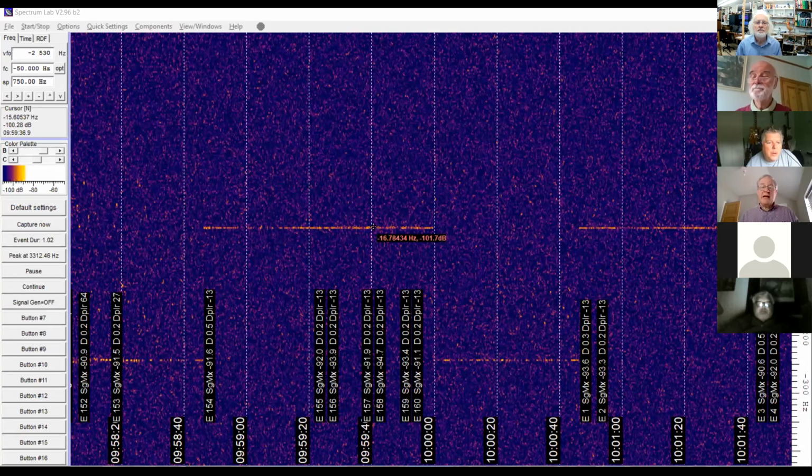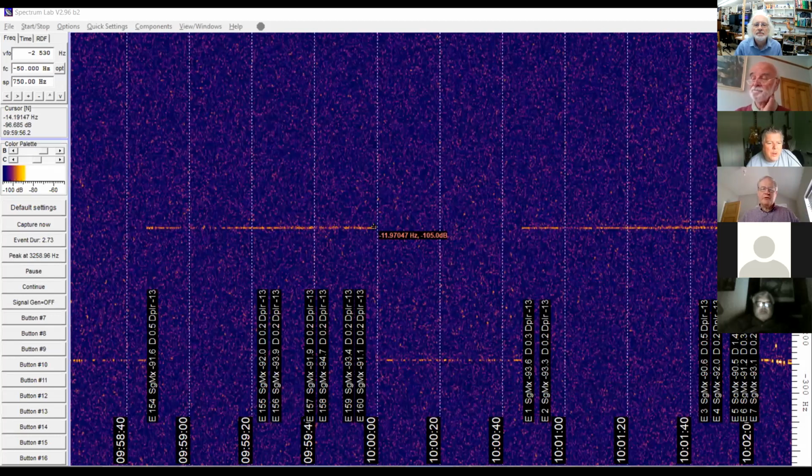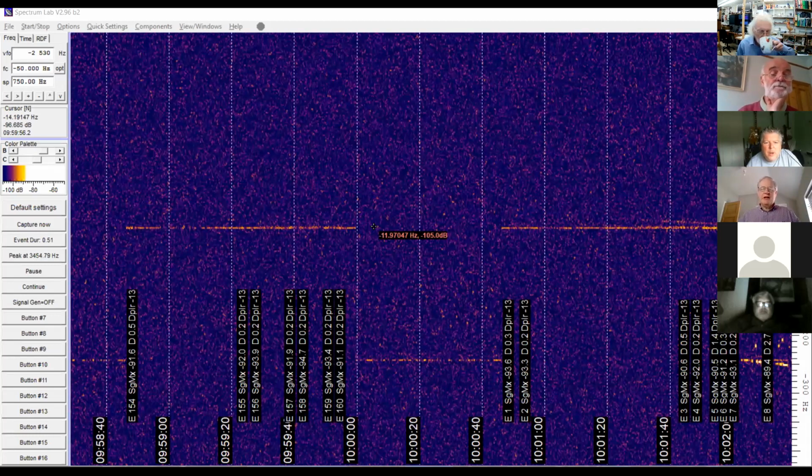But the center line in between the tone bursts is a precision fixed frequency, GPS controlled, so you know it's precisely 144.43 megahertz. The tone bursts, which happen every 2 minutes, provide a nice way of confirming that it's the signal you're after.